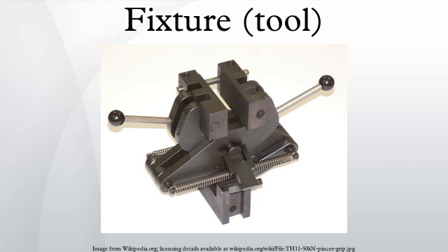For locating workpieces, fixtures employ pins, clamps, and surfaces. These components ensure that the workpiece is positioned correctly, and remains in the same position throughout the operation. Surfaces provide support for the piece, pins allow for precise location at low surface area expense, and clamps allow for the workpiece to be removed or its position adjusted. Locating pieces tend to be designed and built to very tight specifications.